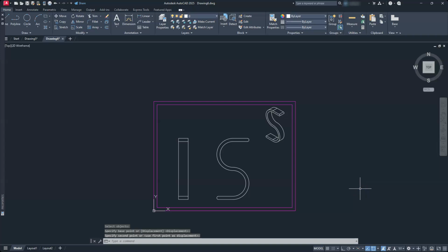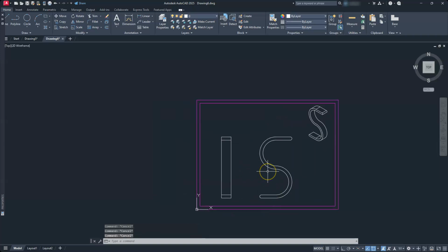Okay, so now you see that this is kind of what we would typically have for this. And I can move these around or do what I want to do with them. Now, as far as putting dimensions on, always start with your center lines and your center marks first. But before I do that, I need to tell AutoCAD that I've adjusted my scale factor, right? My scale factor is 20. At this point, you have to decide which method you're going to use. I like to break them down as calling it a standard method or an annotation. Since we're doing this in model space, we're not using paper space, so we only have these two options, standard or annotation. We typically use annotation. Annotation is nice and easy. If I select this flyout and I select 20, it's easy.